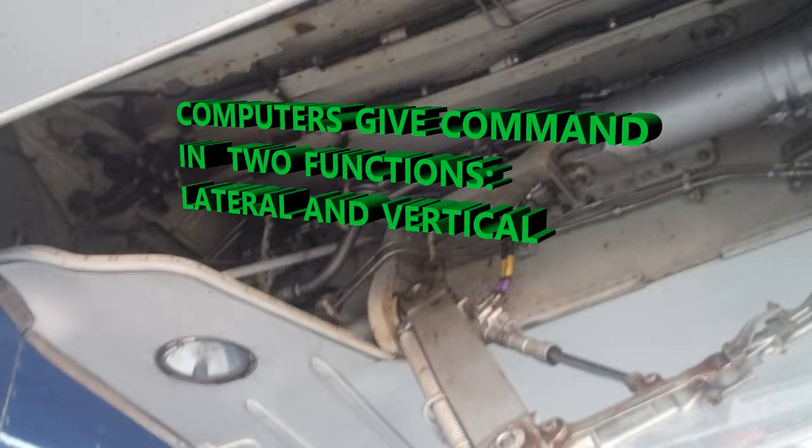The idea with the primary flight control system is being able to have the airplane flying safely in all directions that the plane flies in, all three axes. Remember we mentioned before the pitch, yaw, and roll. The way this is classified as far as the computers giving command orders is in two different functions: your lateral function and your vertical function.